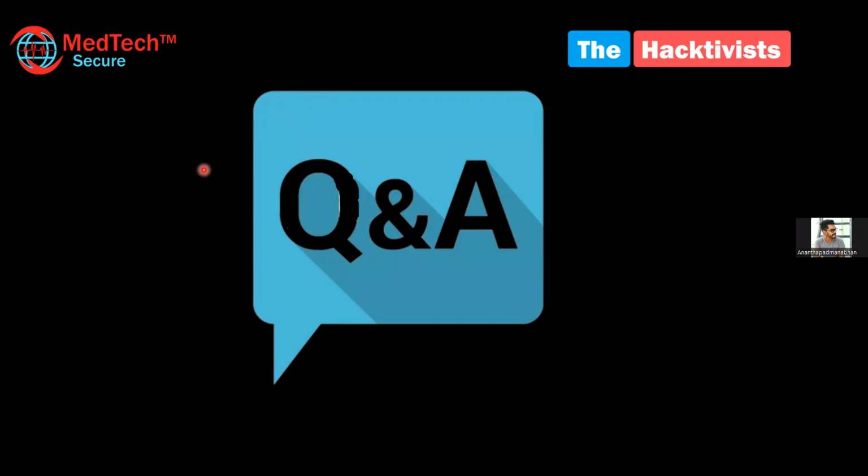Yeah. Suppose that device is using an STM32 chipset, and it has any external peripherals like flash or any other interesting components, we can perform those test cases. Also, suppose from that STM32 you find out what kind of protocols it is using, then you can perform protocol-based security test cases. In today's session we just looked into UART, but if it is using SPI, JTAG, or I2C protocol, based on those testing points, we'll use different devices.